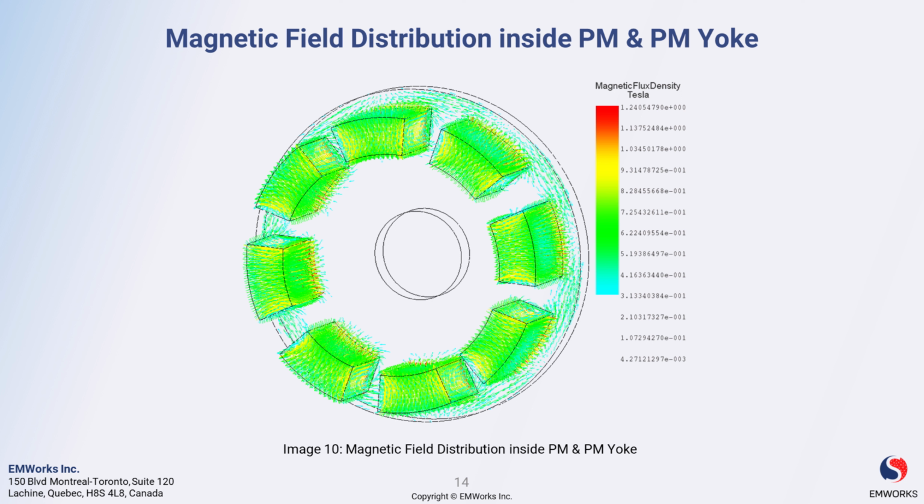By analyzing the magnetic field distribution, we can identify potential areas for improvement or optimization. For example, if the distribution shows a region of high magnetic field concentration or saturation, adjustment to the magnet configuration, material selection, or geometric design may be necessary to improve the magnetic circuit, which in turn reduces losses.